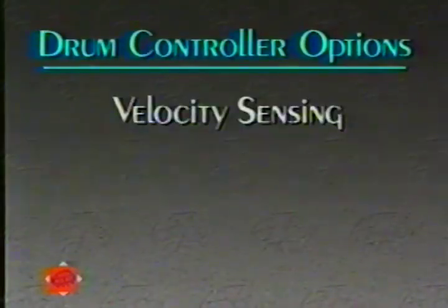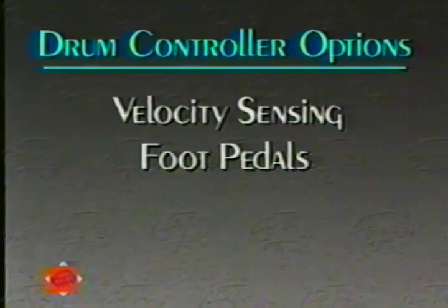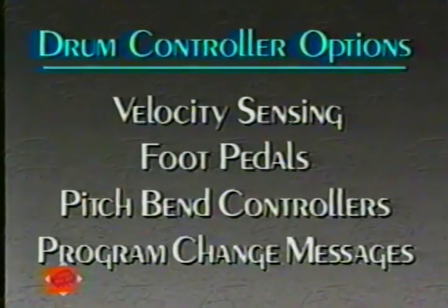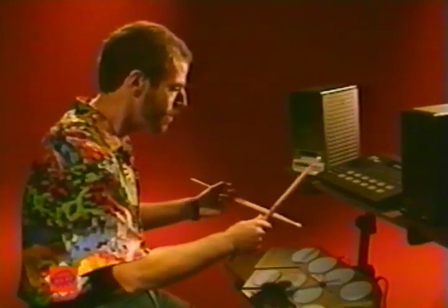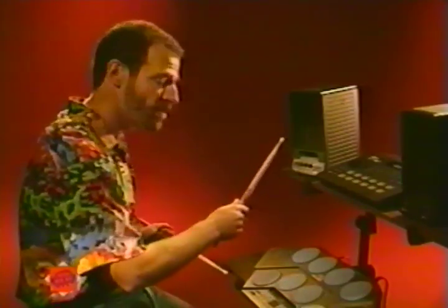So look for such features as velocity sensing, provision for foot pedals and pitch bend controllers, and the ability to send MIDI program change messages. I also like to be able to assign each pad its own MIDI channel number, so that each pad can control its own synthesizer or its own patch. Sometimes I even use patches that make sounds we don't expect from a drum. After all, drum controllers produce note-on messages just like a keyboard or wind controller.